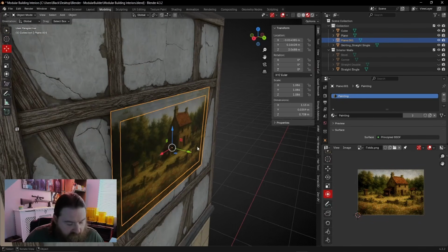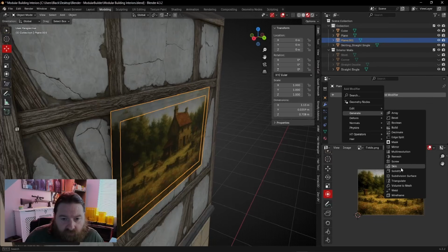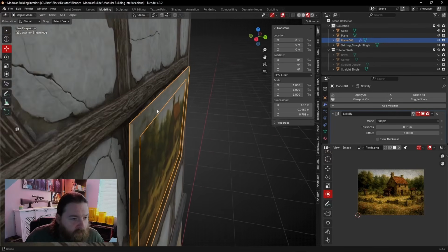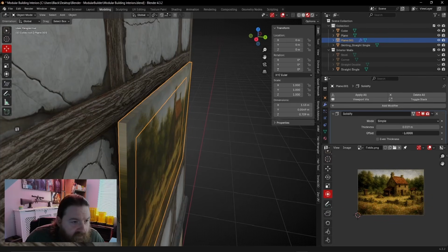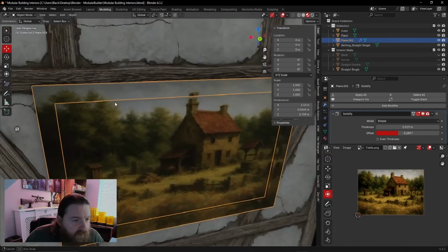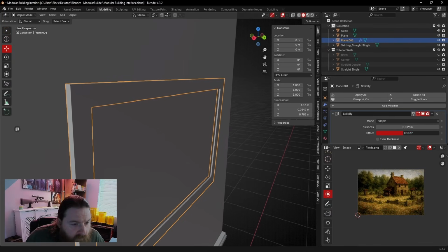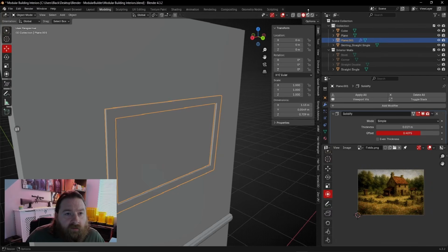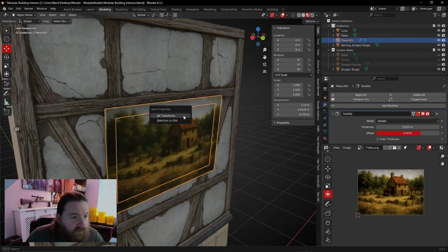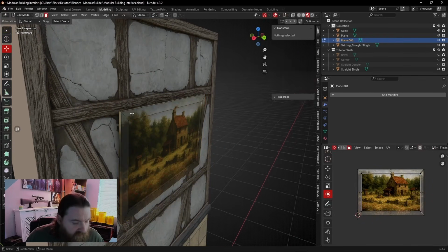And now I can give this a solidify modifier. We'll give it some thickness. Generate, solidify, and yeah, we will get this to generate backwards and then offset it in the front a touch. Maybe if I come into gray shade, I could see this a little better. Something like that is fine. Right. Now, I just need to apply this.